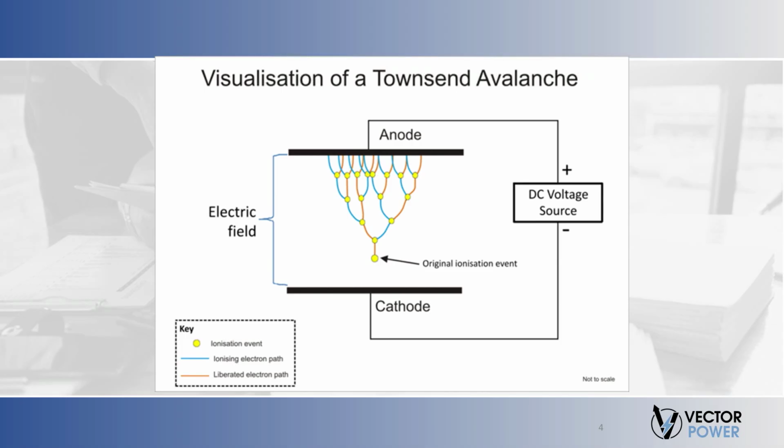These discharges do not completely bridge the insulation between the conductors. The defects may be located entirely within the insulation, along the interfaces between different insulating materials, or along the insulation surfaces, such as terminations or potheads.